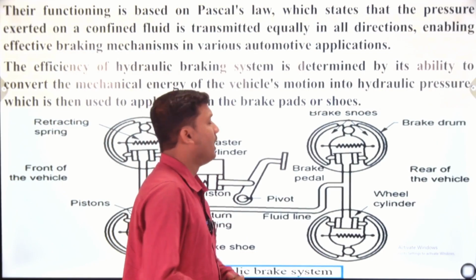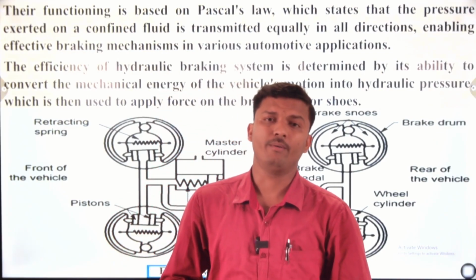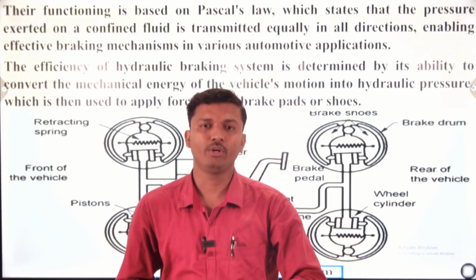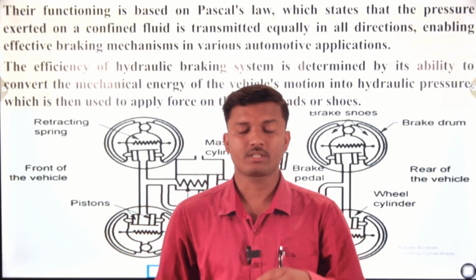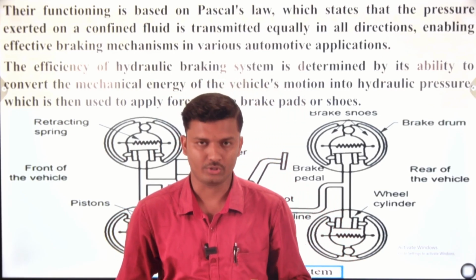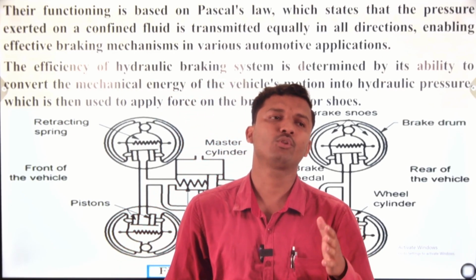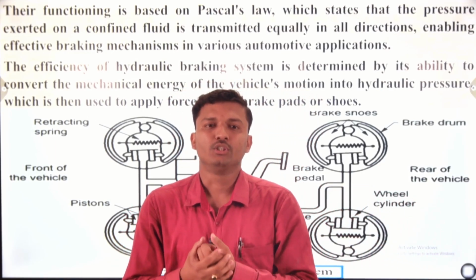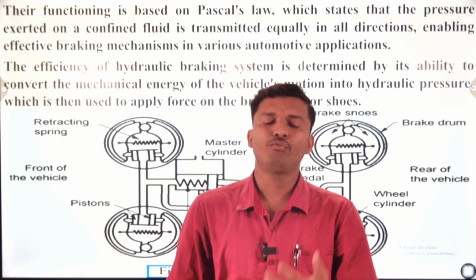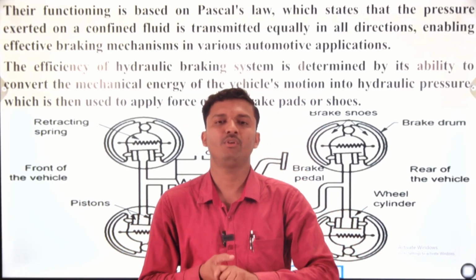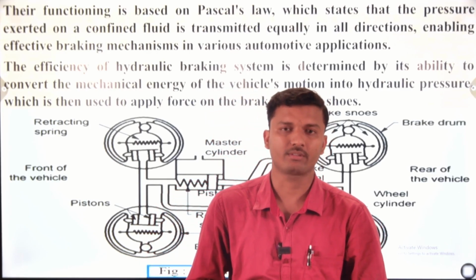Next, which physics law is the functioning of the hydraulic brake based on? It works according to Pascal's law. In Pascal's law, what happens? The fluid gets distributed equally throughout the system, by application of force from a single point. The pressure exerted on a confined fluid is transmitted equally in all directions, which enables an effective braking mechanism in various automotive applications. This is Pascal's law.